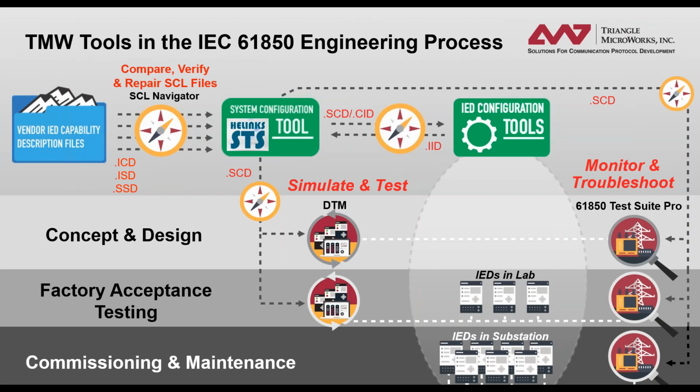Will SCL Navigator verify all test conditions for ICD based on conformance? Well, the conformance is testing at the SCL level, testing the file's correct according to the standard, which is what the Verify tool does. So I would say yes, it will verify that you're conformant.